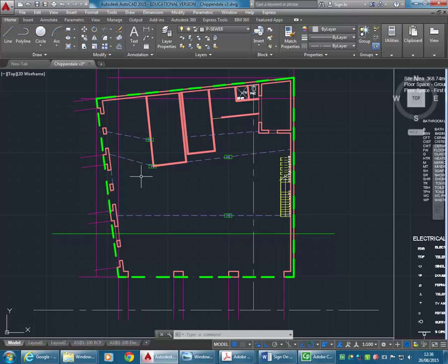And they've got to have power, and they do make a bit of noise. So anyhow, it's one of those things you have to know about every aspect of life when you're designing. Just think about those things. And if you can do it in the traditional way, which is to have risers that connect to the easiest connection to the sewer, then you're usually better off.